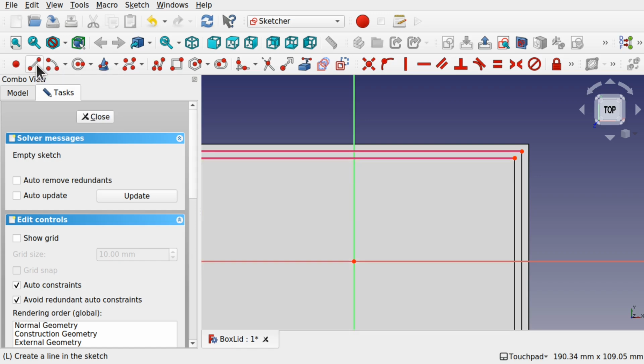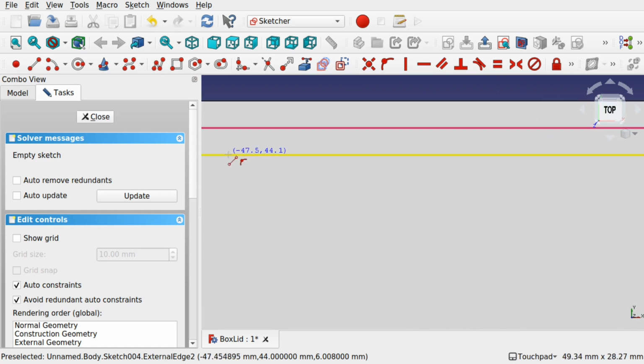So I'm going to create a line. We can create an L shape or a line, it's up to you, but it's always the way this is created. So watch the way we work with this. I'm going to work from inside out. So I've got the auto constraints on, so I'm auto constraining to this line. Zoom in a bit. Click, and then I'm coming up. I want my vertical constraints on.